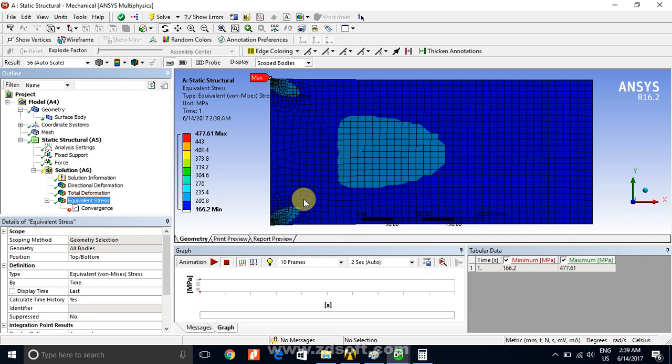So why is the stress increasing? Finite element mechanics says that when a singularity exists in the body, the stress at that location would be infinite. The same thing is done by this FEA: it is moving towards this infinite value.